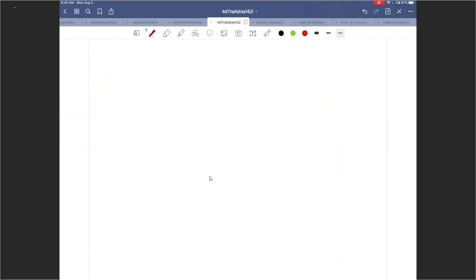If you think about 2 consecutive ones, we are after 2 consecutive ones. The moment you have 2 consecutive ones, that's when you want your output to go to 1. So let's just come up with an arbitrary bit sequence and try to answer the question that I asked earlier.